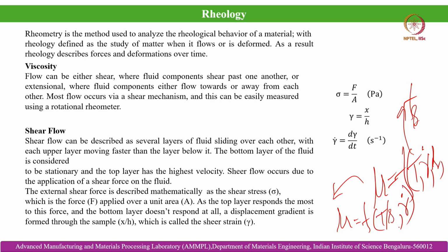That is why it is very important to investigate the viscous evolution, the rheological behavior of the solidifying liquid melt, because that decides whether the die design or the process parameters adopted for casting will be successful in achieving a part of sound structural integrity, or whether there will be defects or the required microstructure will not be generated upon solidification.